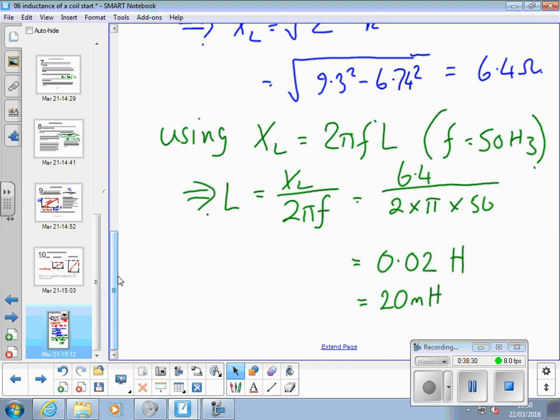And you're going to do that in your practical work, with a variable inductor at various positions. Actually, we're on a different coil of wire, a different inductor. Chris has measured, I've measured the inductance using this method, and Chris has used an inductance measuring instrument costing about £2,000, and the results concur.